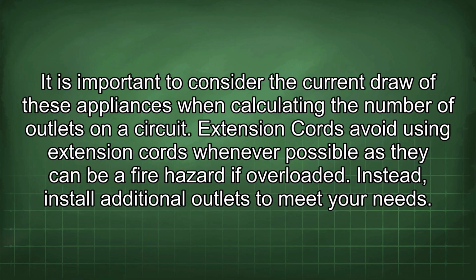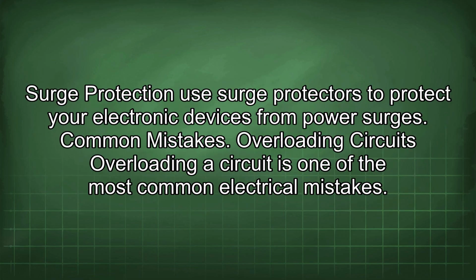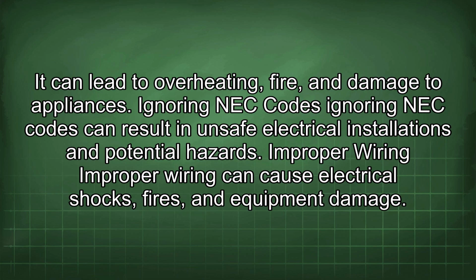Extension cords. Avoid using extension cords whenever possible, as they can be a fire hazard if overloaded. Instead, install additional outlets to meet your needs. Surge protection. Use surge protectors to protect your electronic devices from power surges. Common mistakes. Overloading circuits. Overloading a circuit is one of the most common electrical mistakes. It can lead to overheating, fire, and damage to appliances.